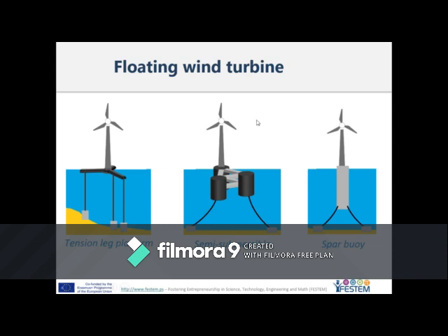We have another structure we call a floating wind turbine. That means we don't have the foundation, we don't have to stick to the ground, and this works very well in deep water. Here we have a tension leg platform, we have weights here, and they're connected to the underground, so as to keep this wind turbine structure vertical.